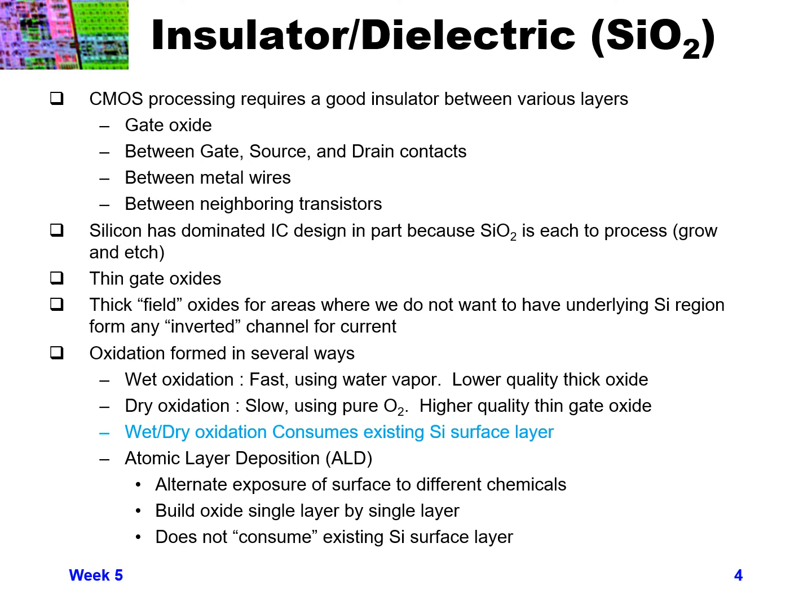Another way to form oxide is what's called dry oxidation. Instead of using water vapor, we use pure oxygen flowing over the wafer while we heat it up. This will grow oxide pretty slowly, but it forms a really high quality oxide with predictable thickness, and we can form our gate oxides using dry oxidation.